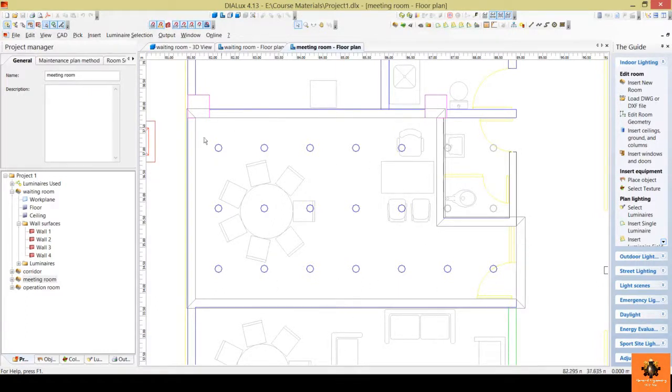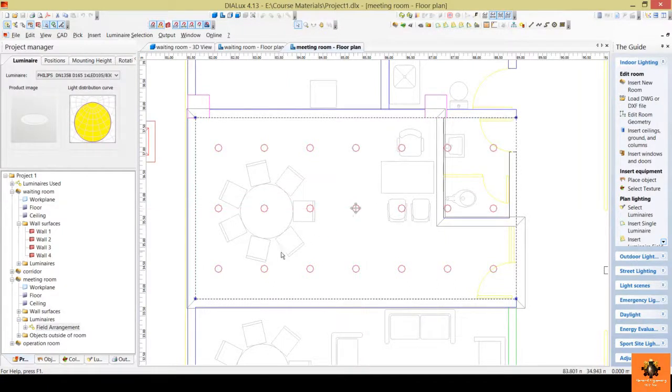So 4 luminaires of those 17 luminaires will be fed with 2 sources, as they will be used as emergency luminaires, so in case the main power source is getting off, those 4 luminaires will still be working, as we have another power source that is feeding those 4 luminaires. And we can select those 4 luminaires to be this one, for example, and this one, and we can select the third one, and we can select this fourth one, for example.